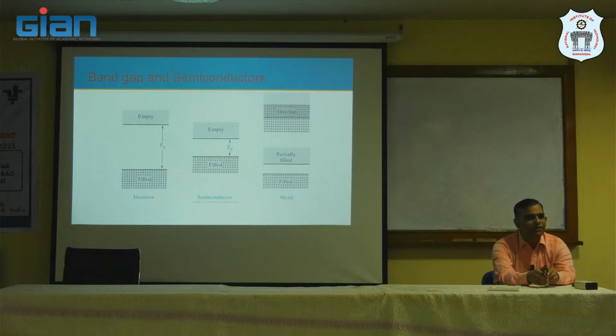You have your mobile phones? 1.12 electron volt, right? So, that is the energy I have. That is the band gap I need to overcome. Now, the question is, what is the highest wavelength I can measure with 1.12 electron volt? You have 1.12 electron volt on one side and hc by lambda on the other side. Let us try to find what will be the lambda.